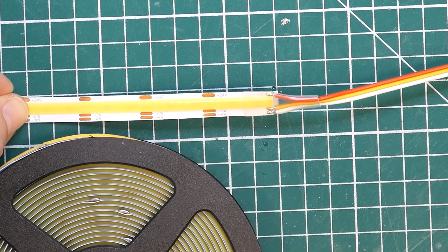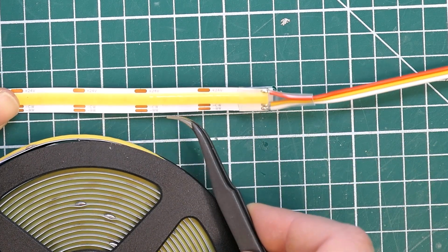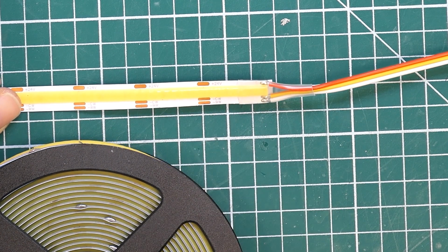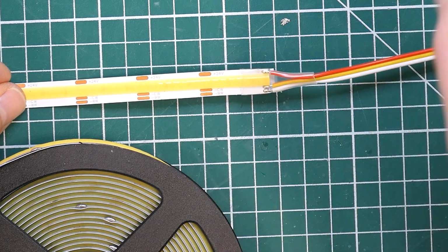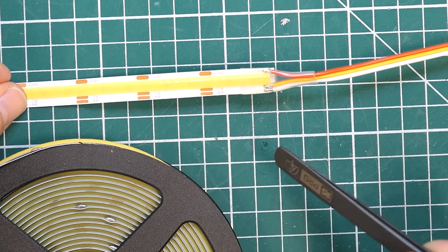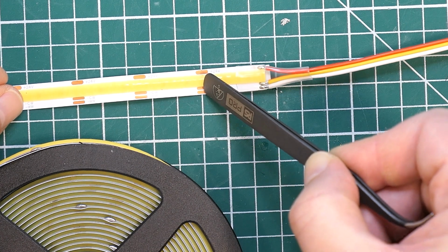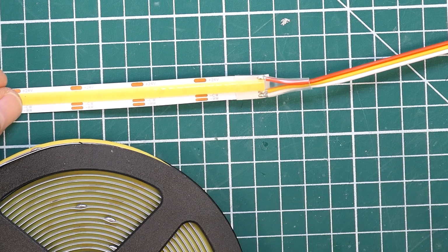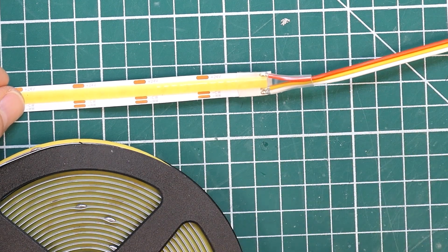And here's the actual LED strip. You can see there's quite a lot of them. And if you look closely, you can actually see they're printed with the particular assignments of what each pad is. So you can see the plus 24 volts. You can see the CW and the warm white as well. You don't have to use those wires for connecting to the strip. You can actually solder to any of the copper pads and it'll work. And you can cut the strip at any of the copper pads as well. So that's also really helpful, as you'll see later in the video.